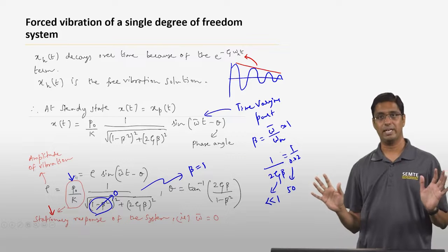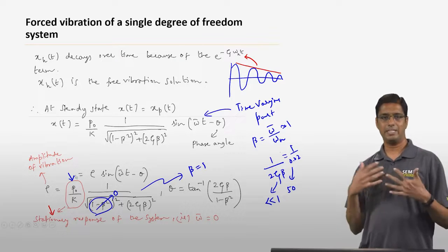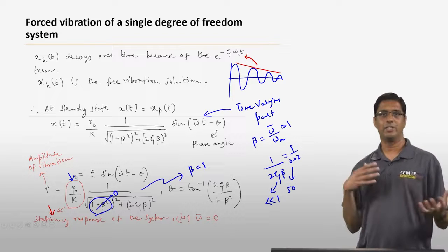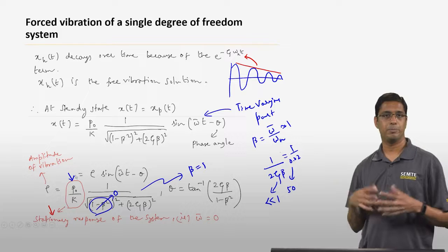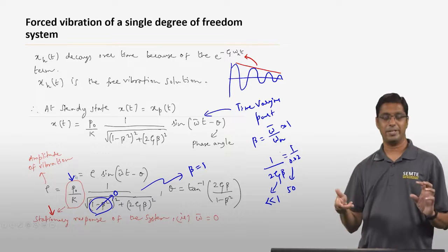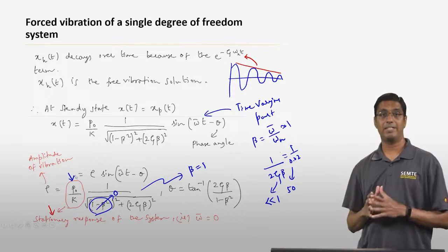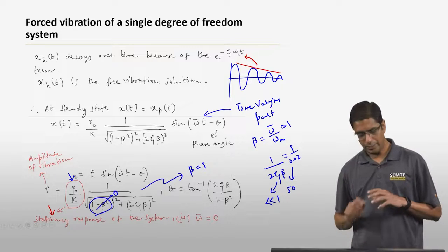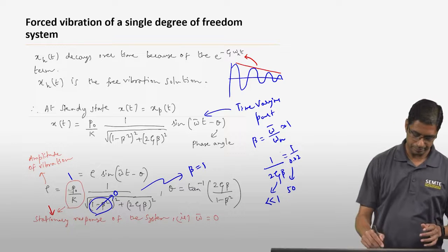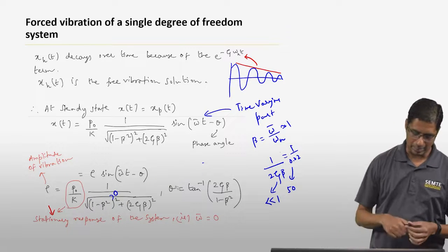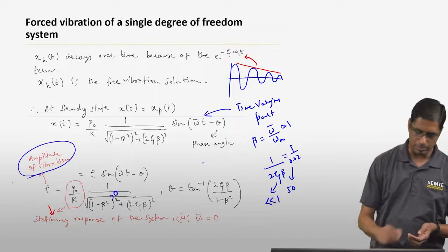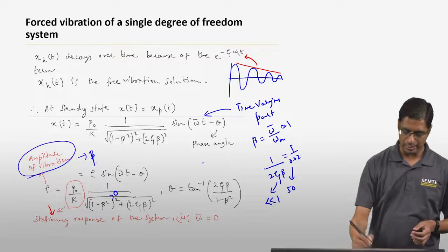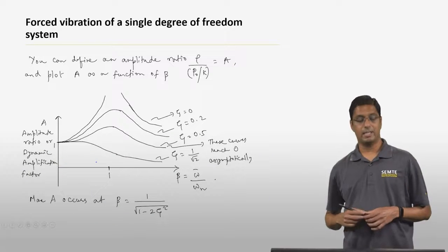very quickly. Okay? And that's why when you look at actual mechanical systems that are rotating, systems that are translating, systems that have torques being translated, motors being rotated, then the vibration aspect becomes as important as anything else. Okay? Now, you can take this rho, which is the amplitude of the vibration, and then plot it as a function of beta. Okay? And if you do that, you essentially will get curves like this.